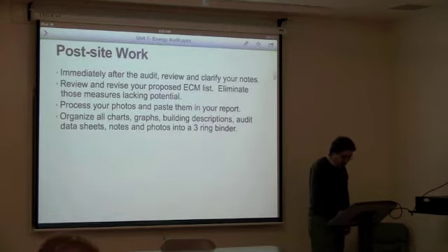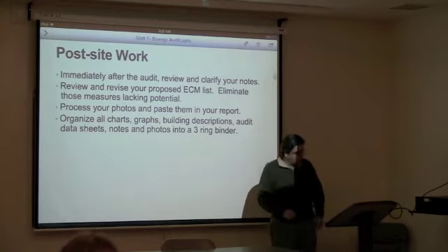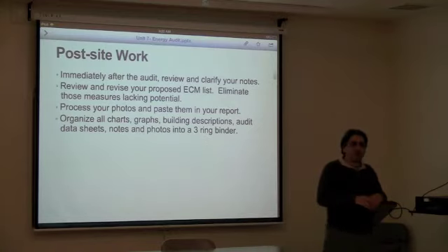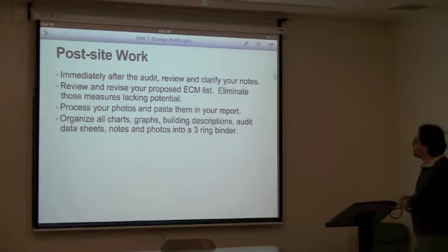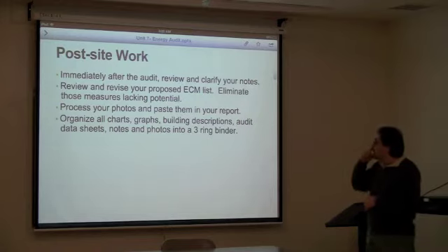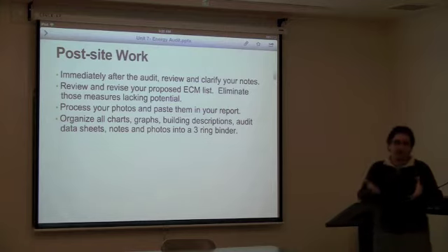Talk about sitting with the energy managers. After you have collected all of the information, you go back to your office and start the post-visit cycle. The very first important thing you have to do is list all of the energy consumptions, from top to bottom, and try to create a report and analyze your photos. Most of the time, I not only take photos, I also take video.